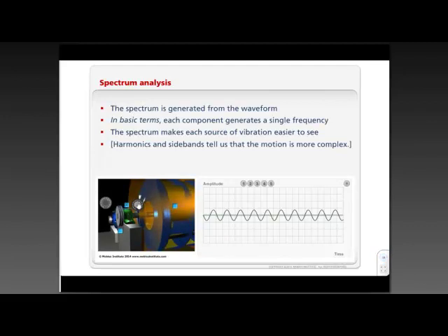In actual fact, there's a few. If the bearings were in good condition, we wouldn't expect any vibration at that unique frequency. As those balls just roll along, or the rollers roll along, there is no special vibration. But if there is a problem, we get some vibration at a unique frequency. As I said, it's actually 4 unique frequencies for bearings, but we get this green source of vibration from our green bearings.